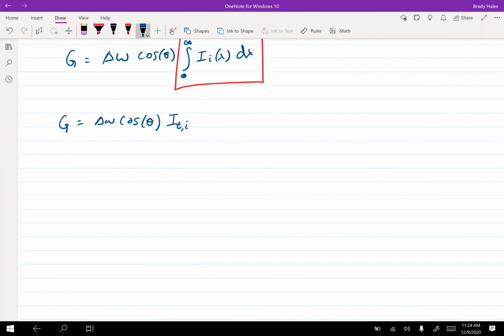So this is where you have to go back, and what you want to do now is relate it to something like emissive power. The Stefan-Boltzmann law says that the emissive power of a black body is equal to sigma Ts to the fourth. Then you ask yourself, is the sun a black body? Yes, it's a black body, so we can use this law. If it wasn't, the emissive power for a real diffuse surface is epsilon sigma Ts to the fourth. But for a black body, emissivity is equal to 1.